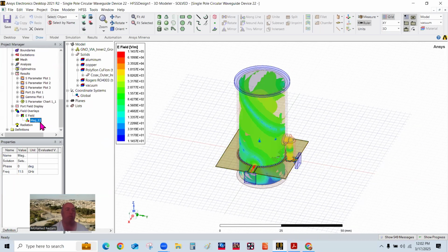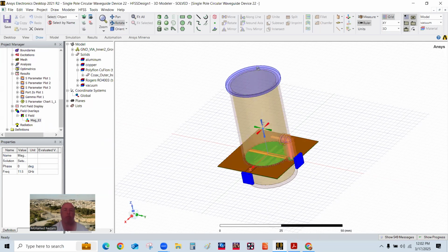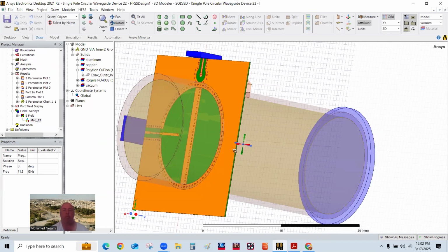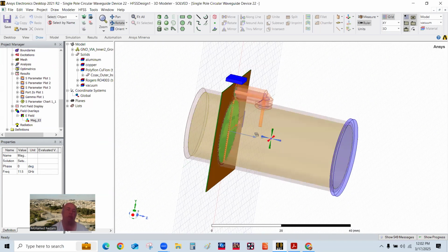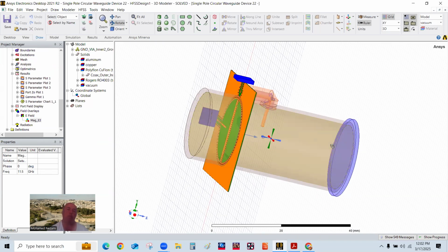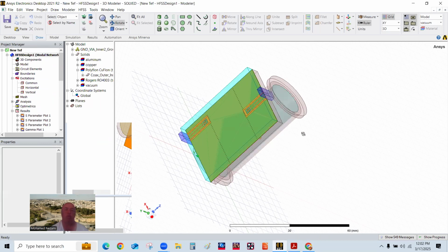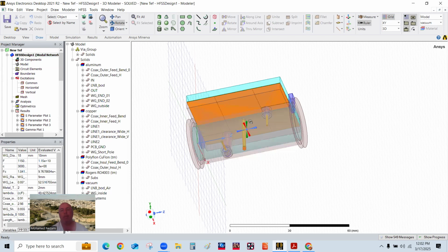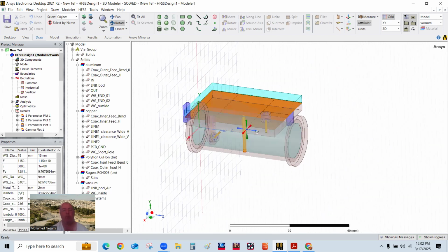And let me just quickly show what I had to do. I had the board in here as the circle we got, and the board now is actually on the other side. It's perpendicular to the waveguide, and that's one of the trade-offs. There's the difference: in this one here, the board really is in parallel to the waveguide. So in a lot of cases, that's why this one is preferable.